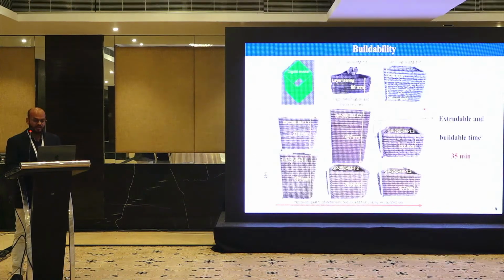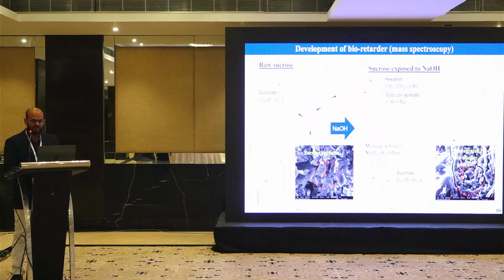The buildability of the material has also been tested. In the control mixes, two mixes, the buildability is lower. In the soil-based mixes, the buildability is very high. But one important aspect is that the extrudable, buildable time was only 35 minutes.